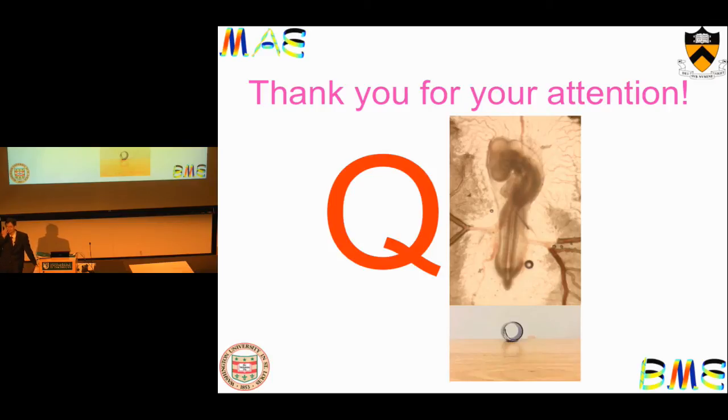I understand how you make your stretched latex models. How is the bracelet made? The snap bracelet. Oh, this one. I think the idea here is to induce plastic deformation in two directions, such that locally it has a tendency to bend in this direction, and a tendency to bend in the other direction. Then, because of these geometric nonlinear effects we talk about, it has to adopt a nearly cylindrical shape, so it has to choose one shape or the other. In fact, if you cut the snap bracelet down to a small enough piece, it loses this bistability and becomes just a saddle shape.